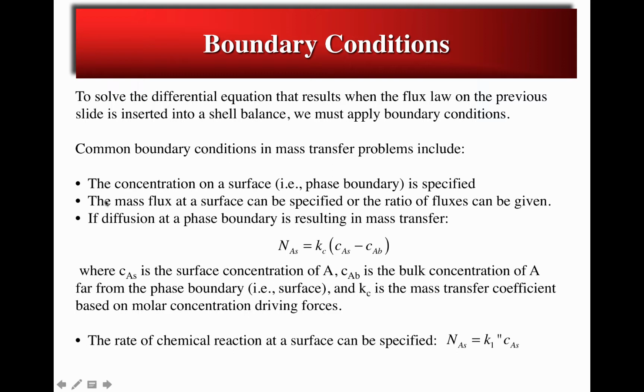For example, the concentration of a component at a phase boundary, like a gas-liquid interface, may be specified. Typically, thermodynamics might govern the concentration, for example, of a gas dissolved in a liquid at a gas-liquid interface. Alternatively, the mass flux of a component or the ratio of mass fluxes of components at a surface can be specified. We'll see examples of that later.